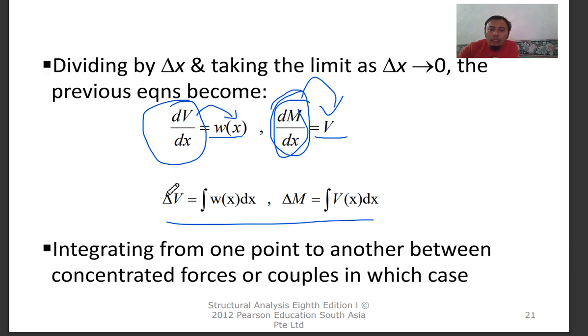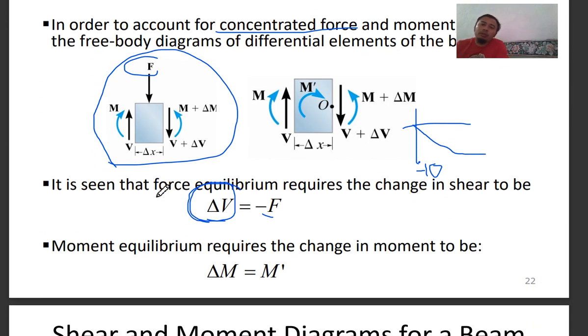Basically, I just want to show you how to differentiate when you are drawing a shear force diagram or bending moment diagram. Having knowledge of the function due to that loading will help you determine how to draw the graph.